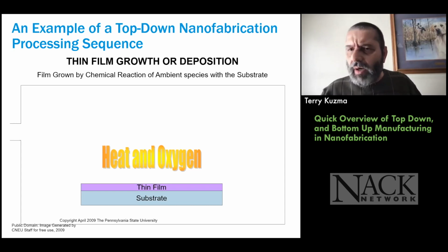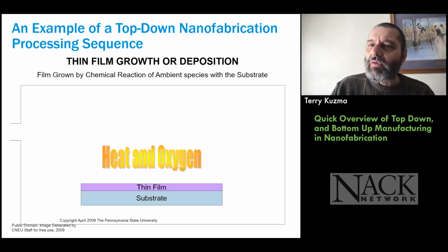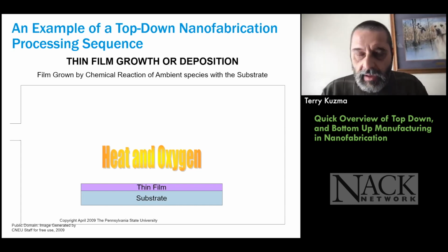Like I said before, 900 degrees Celsius is crazy. And that's where you grow the best oxide. Actually, that temperature is a pretty good sweet spot that most people would recommend, that you would grow your oxide at 900 degrees C. Does everybody see that? That's a really good temperature that most people would respect.